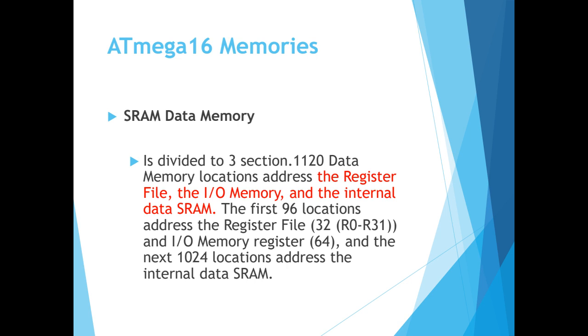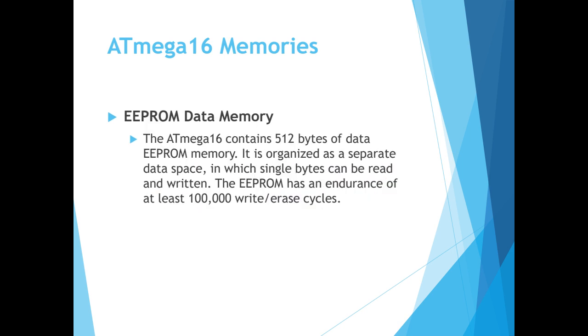As you see, as I said, the first 96 locations address the register file, and 64 locations address the input output memory registers, and the next 1024 locations address the internal data SRAM.